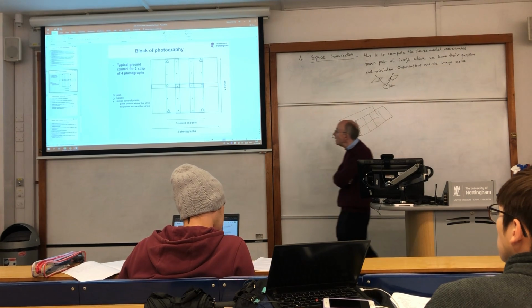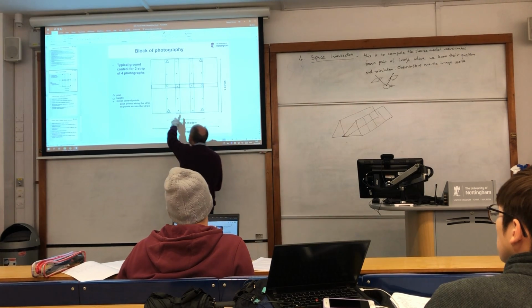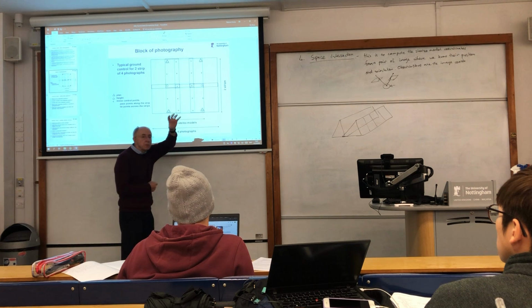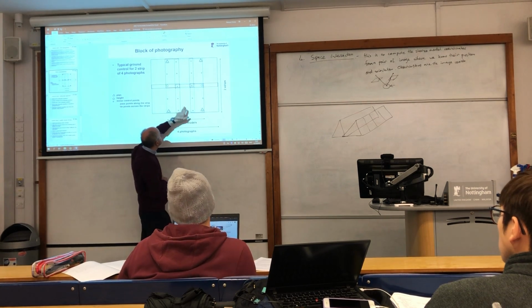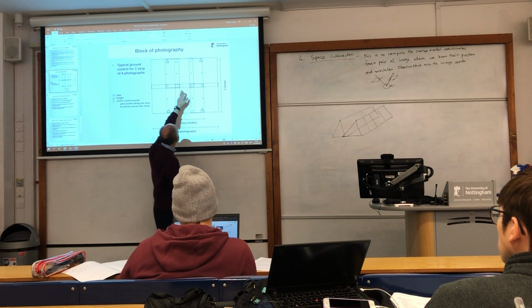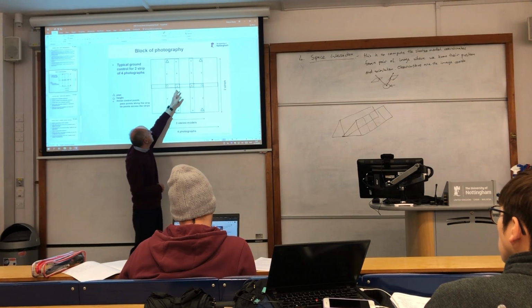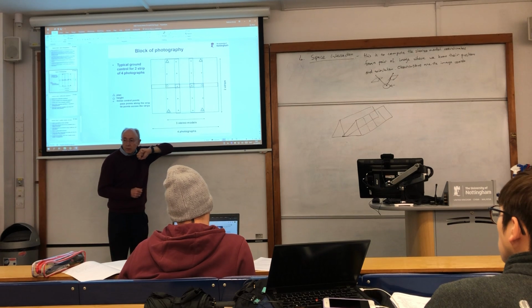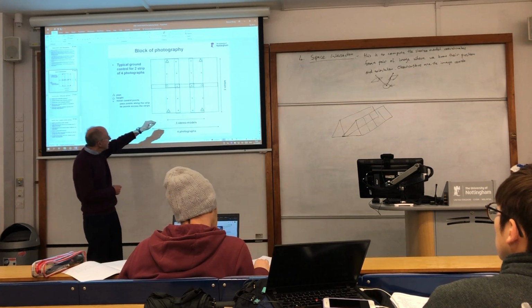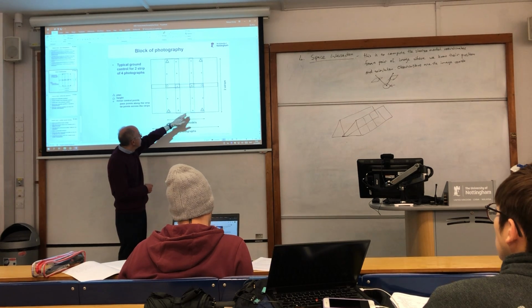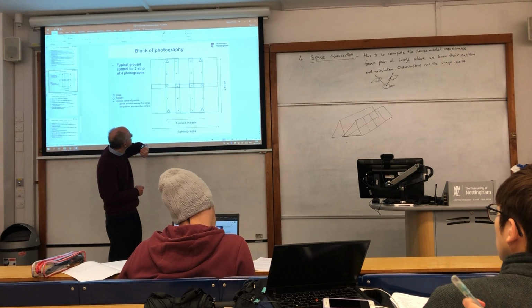and then I would talk about the fact that we need to observe these tie points. This is what the question's about. The tie points between the stereo models, and over here they've got to be in the lateral overlap. Right, so that's the essence of the question, and again it's going back to this issue of where you put the control points.